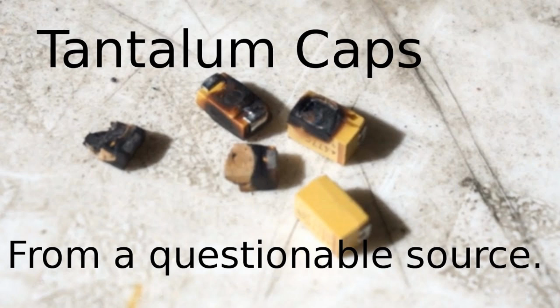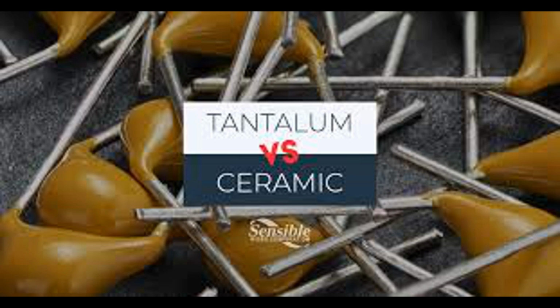In summary, a tantalum capacitor functions by creating a large capacitance in a small volume using a highly efficient dielectric, tantalum pentoxide, and is commonly used in circuits that require stable, reliable energy storage. The construction of a tantalum capacitor involves several key components and processes that result in its compact size and reliable performance. Below is an outline of the construction process.